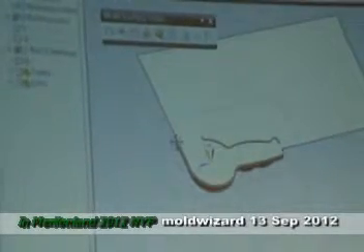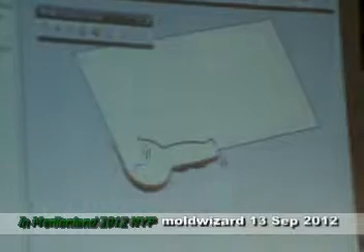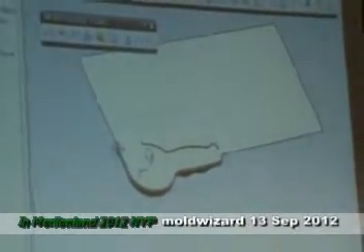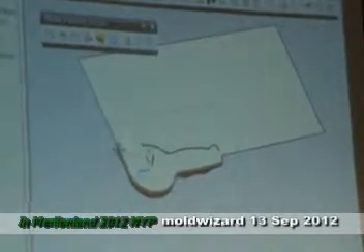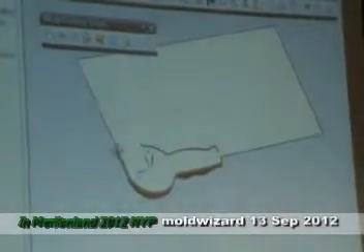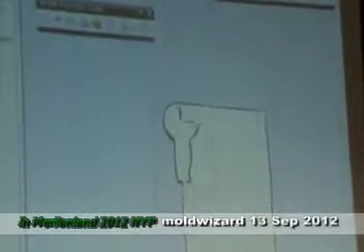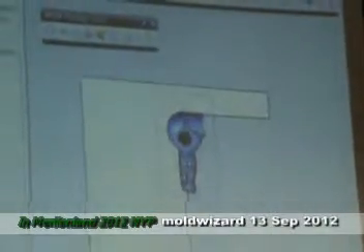This arrow connects with this part of the parting line and will split the planar face into two halves. Of course, we keep one side and discard the other. The system's suggestion is wrong, so we need to flip. We take the other side as our main surface. If this is the correct surface, you can accept it.